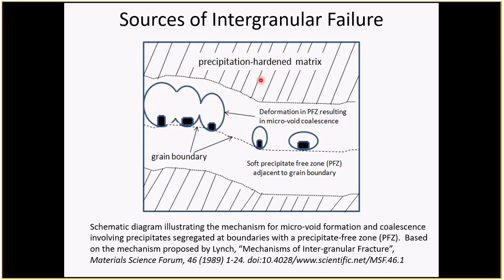But in addition to diffusional creep being a high temperature application, this is outside of the realm of radiation damage now, there is this high temperature grain boundary sliding possibility. And this is where one grain will slide relative to another along a boundary. So precipitating carbides on the boundary actually limits that slip and makes the material more resistant to grain boundary sliding at high temperature.